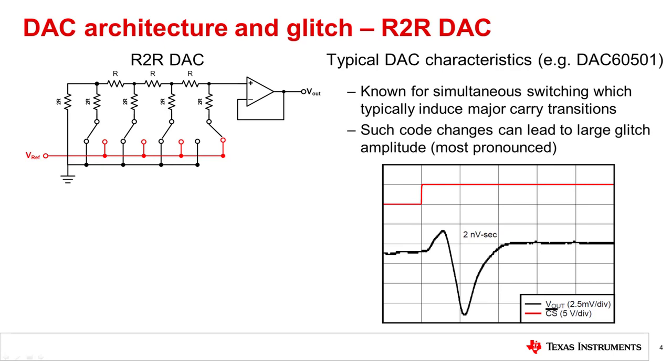In addition, the R2R ladder commonly requires the use of larger switches, which yield higher capacitance. The higher capacitance then increases the charge injection of each of the switches. As a result, you will typically see a signal response as follows. The initial setting of the DAC: at this point, the output is already settled from the prior state as we have just written the new value.